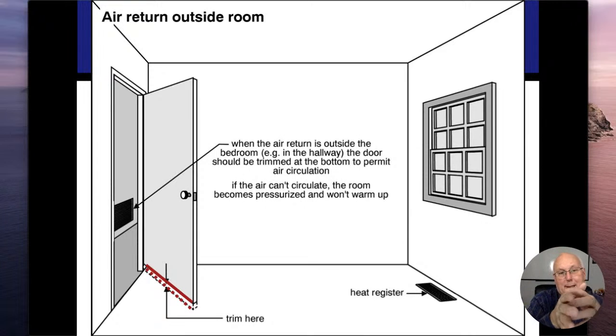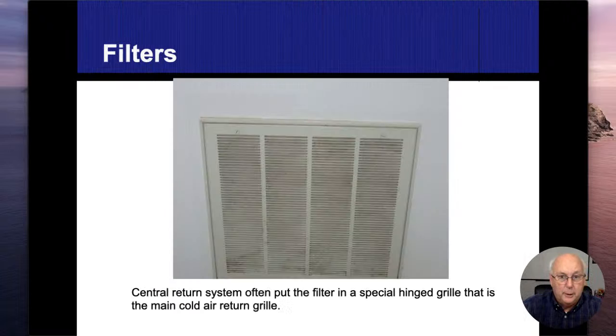And if I get towards the end and it pulls away and kind of slams shut, that's a no-brainer. I mean, something's restricting the airflow out of there. It wants to flow, and we need to let it flow, all right? And so either we undercut the door more, or we have to put in another vent or something in order to let that air get through there.